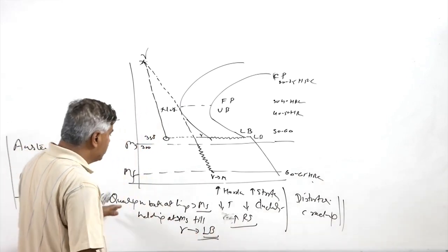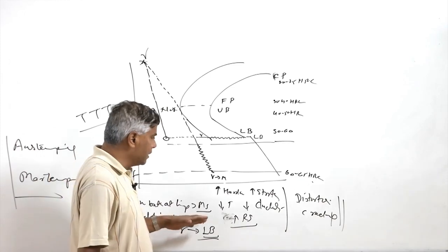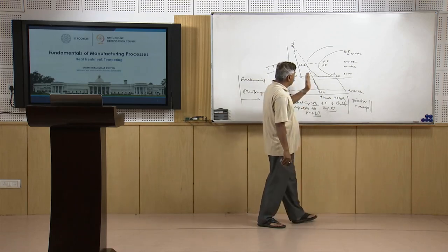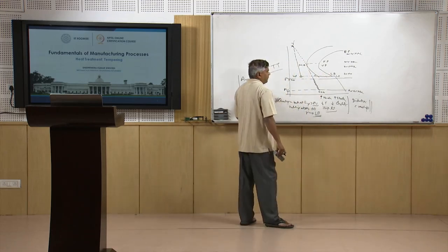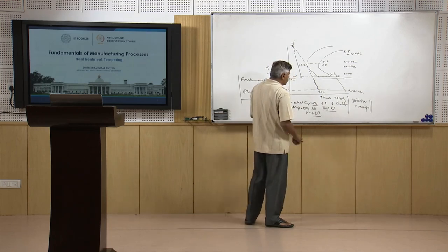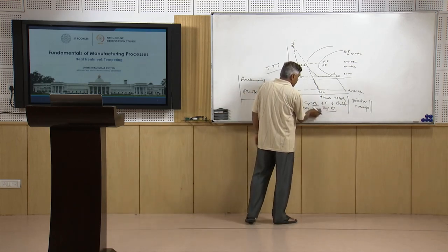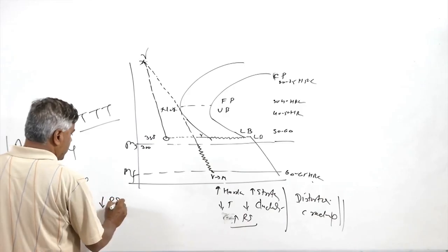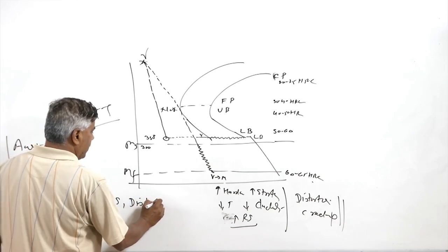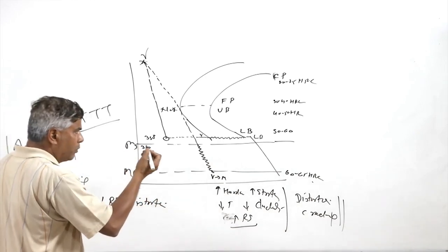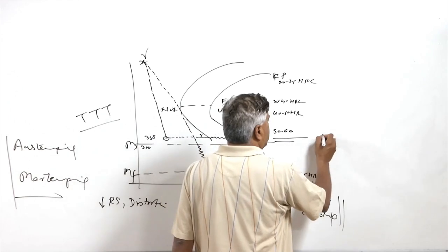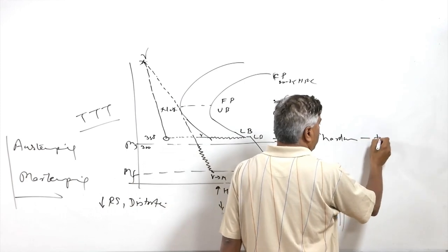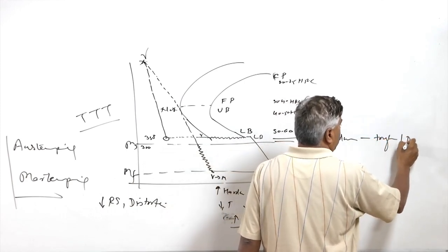So this leads to the homogenization and transformation occurring across the section as a function of time, without differential cooling rates being experienced by the component at the surface and at the core, and because of this we find that the residual stresses and distortion tendency both get reduced, and since it is the lower bainite which is formed, it leads to a significant increase in hardness but without much drop in the toughness and the loss of ductility.